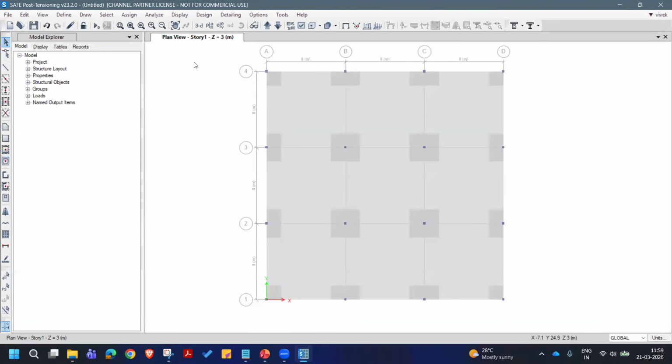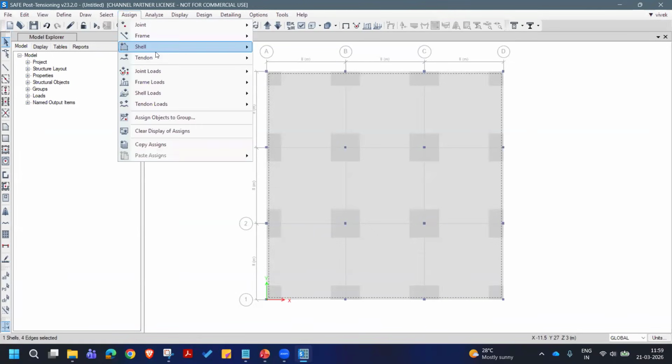That's all. The loads added to these members will be additive, important to note. So you need to select only the floor slab and apply any additional loads to this, dead loads and live loads as usual.